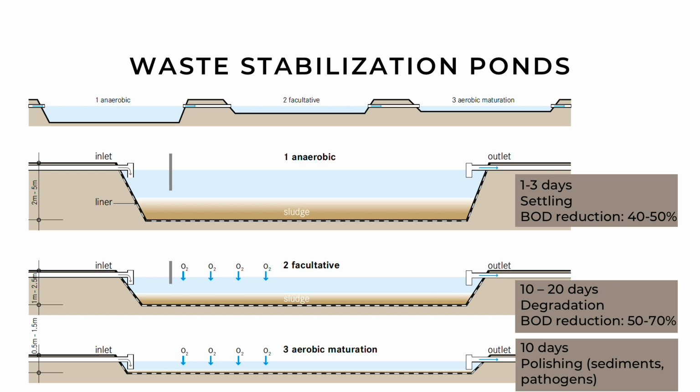Finally, there is a shallow maturation or aerobic pond constructed to a depth of less than 1 meter. Here, the wastewater is retained for about 10 days, which requires a huge surface. In a waste stabilization pond system, this pond acts as a polishing step in which remaining suspended solids, bacteria, and pathogens sediment.